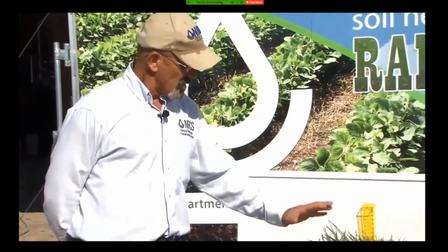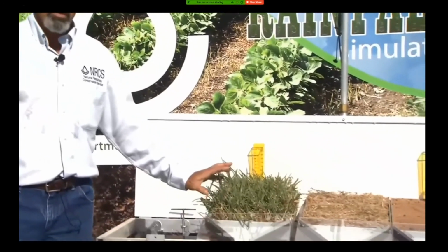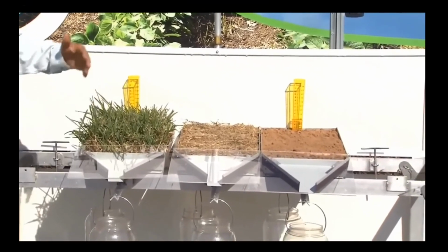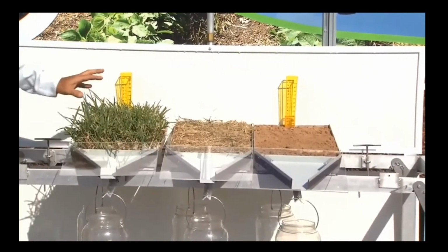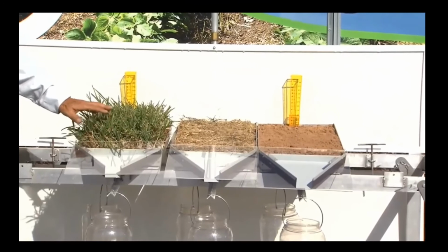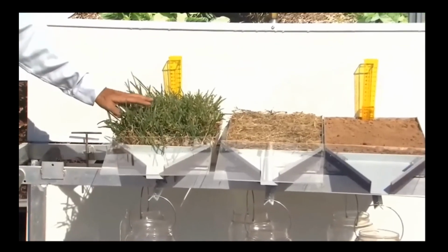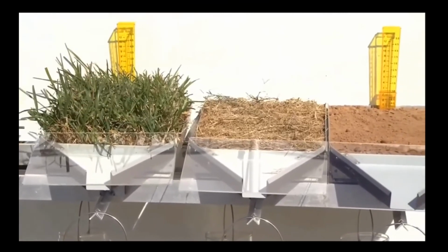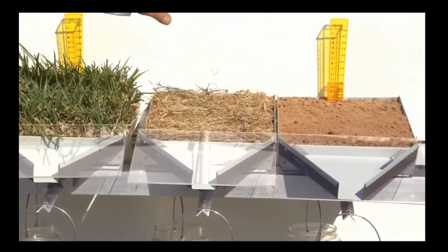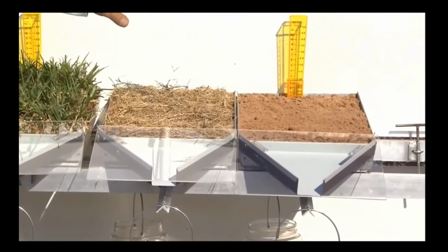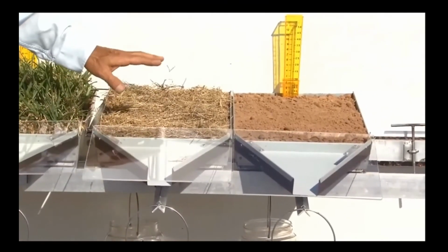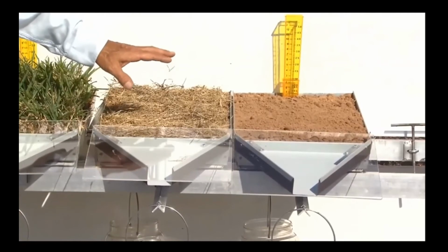Okay. Back to the rainfall simulation unit here. What we have are soil pans packed with soils. These are identical soils taken from within about 3 feet of each other. This pan simulates a natural vegetative cover, thick vegetative cover. The other two on the other extreme, the pan that's been heavily tilled simulates heavily tilled soil, and something intermediate, soil that has been tilled but it has a residue cover on it.